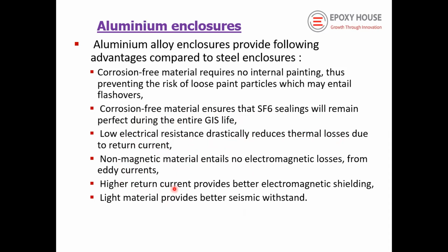Suppose the current conductor is carrying about 2000 ampere; because of induction, about 70 to 80% of the current passes through the enclosure. This acts like electromagnetic shielding.